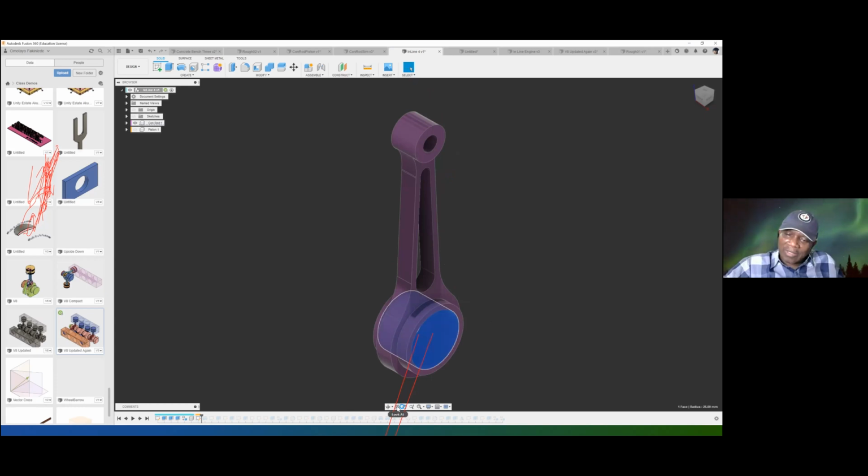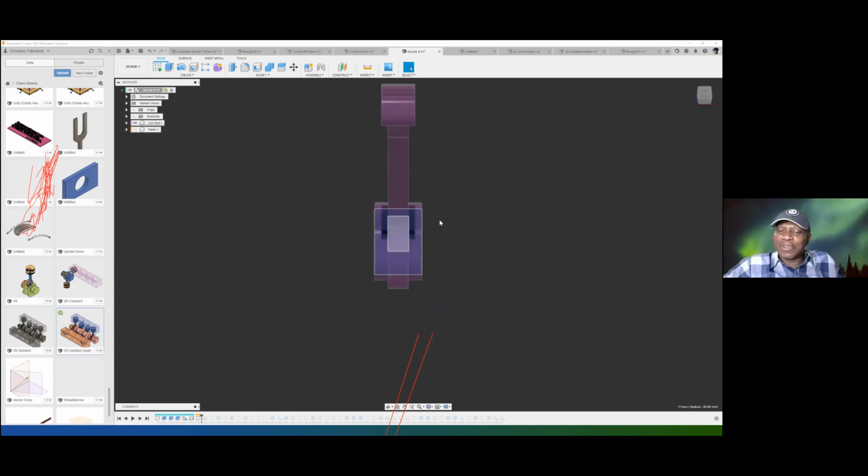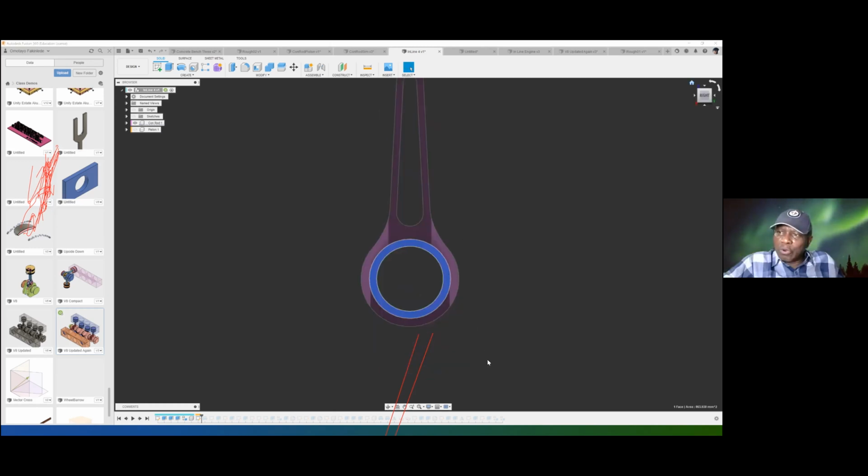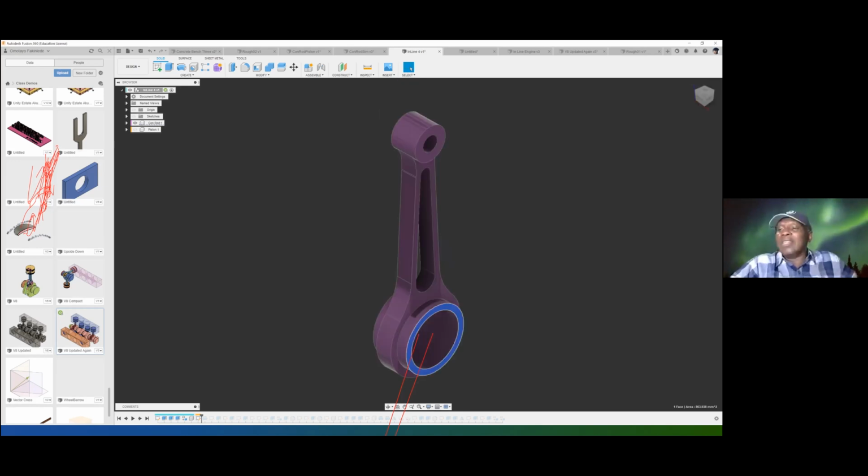It doesn't do anything. Okay, it's difficult because it just looks at one section, and that's all it can do. So when you want to look at a cylindrical surface, it doesn't work, but otherwise it is usually very good. It's a very fast way to look at things. For example, if I want to look at this surface, if I click it and press Look At, it will show me that surface very well. And then I can always return to the home view by clicking home here. You will see later that you can set what that home view should be. This is what is pre-specified in the programming environment. So you can take anything and say Look At, and it will look at it that way.